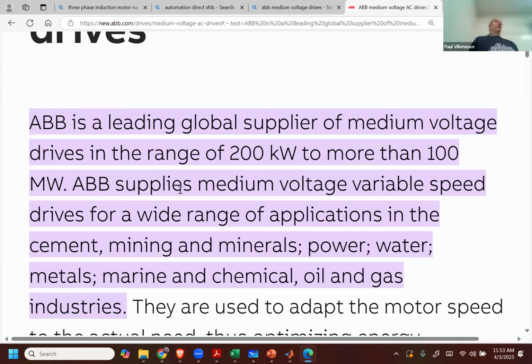If you worked at an industrial facility, everything used to be motor operated valves, maybe a few pneumatic valves to control things. Those are switching to electrically operated valves because you apply electricity and it goes to its position and it's happy to stay there. Air, you need air lines running all over the place. They can get leaks. With electricity, you can use diagnostics. You can do all kinds of different things. And so you're getting more and more efficient.